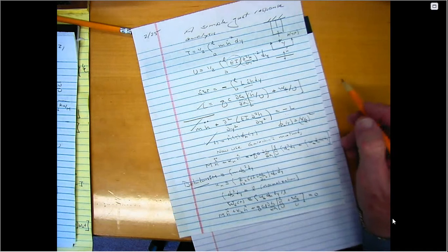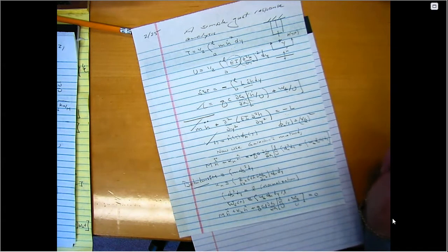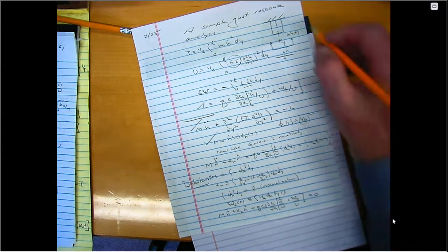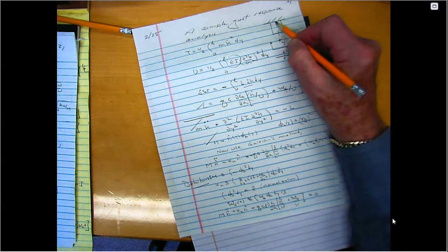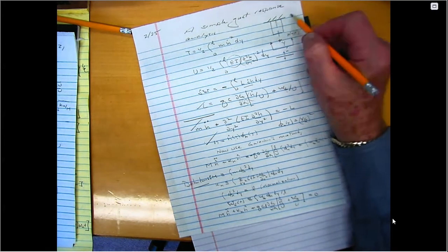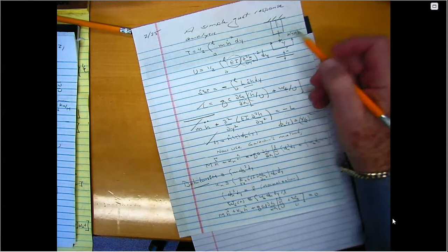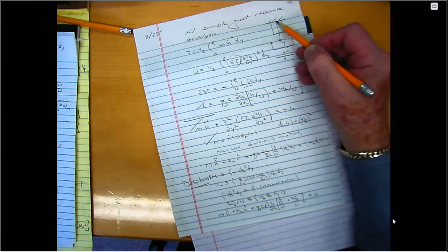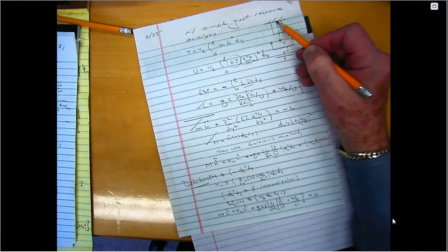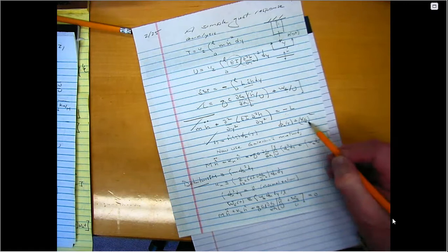I also know that, as you'll discover when you use Hamilton's principle, which gives you the boundary condition, dH/dy at y equals 0 is also 0 if this is clamped, so that not only can the root not translate, it can't rotate locally. So the slope of H, as well as H itself, both of those are 0 at y equals 0. And that's true, right? You can't rotate locally?